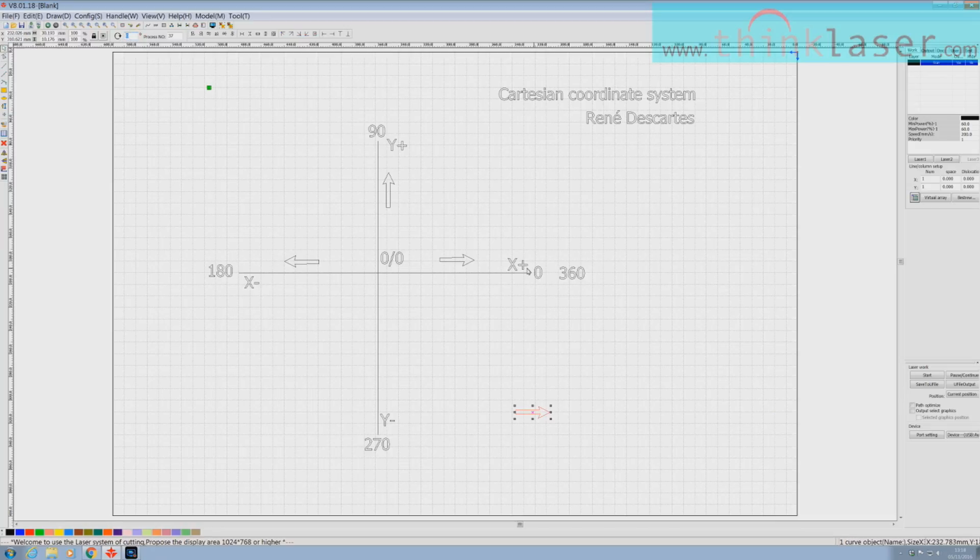But equally well, look, this is 0 plus 90. If we go from 0 to minus 90, we get to 270 as well. So instead of writing 270 in there, perhaps we can write minus 90. So minus 90 works as well. Why have I bothered to show you all this? When we set our machine up, it's the same corner as this corner here.